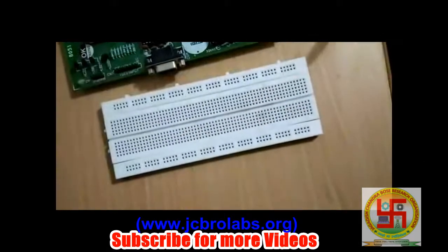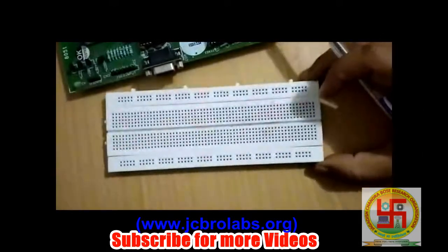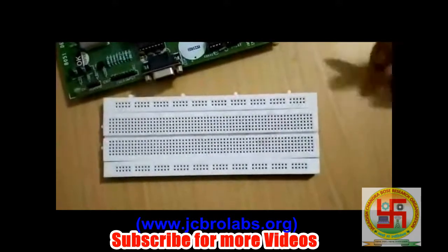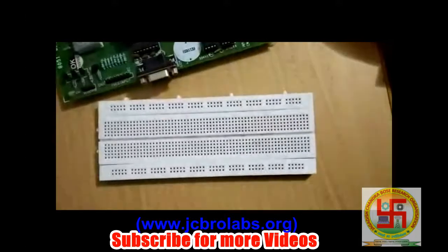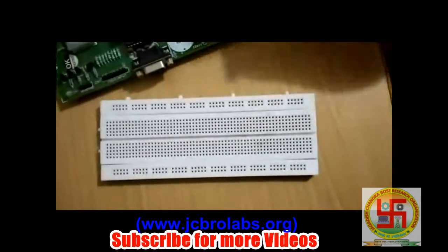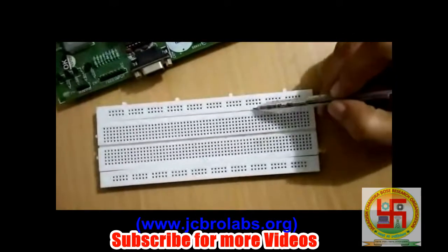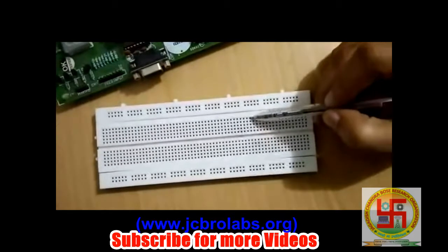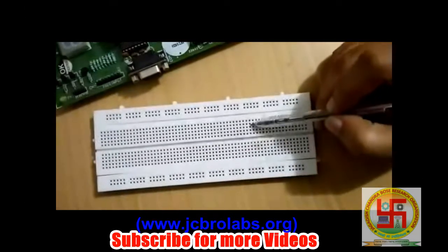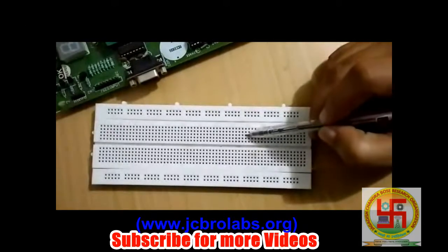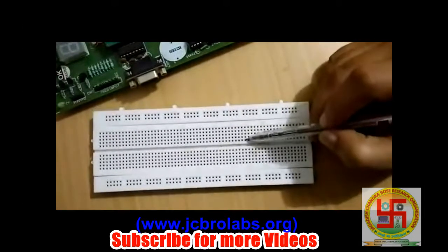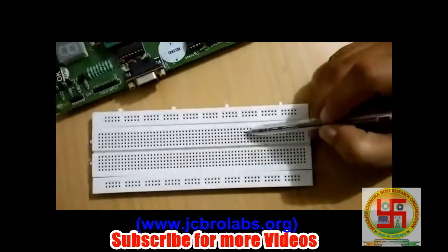So this is a breadboard, as we have discussed. There are several dots which are used for prototyping any circuit, and as we discussed, the dots in this section are shorted vertically like this. That means all these dots in a single column are shorted.